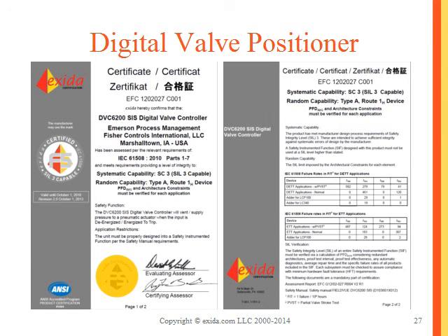This product obviously doesn't know anything about the actuator it's connected to, doesn't know anything about the valve that the actuator is connected to. So for those particular products, you would have to get the partial stroke information from the individual certificates of those products. So that's what that means here. With partial stroke, it doesn't mean that the overall coverage factor is a certain percentage for everything in that final element. It only means that for this particular product, these are the failures that you will detect.